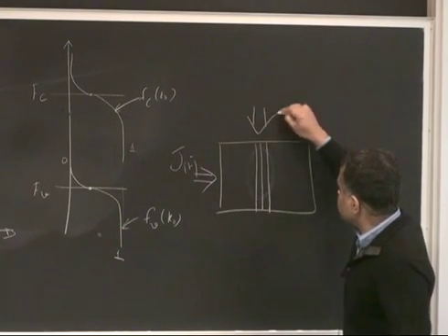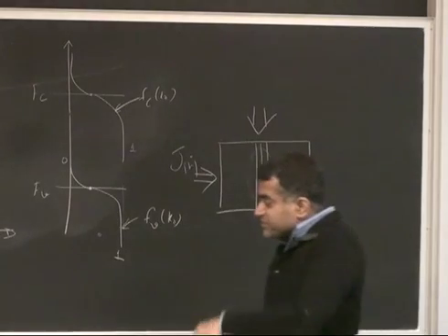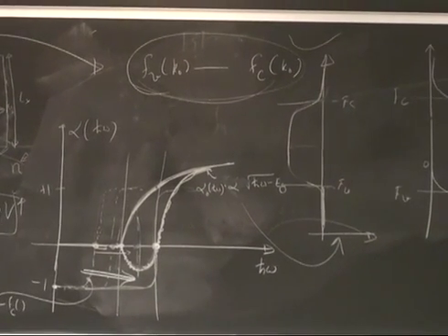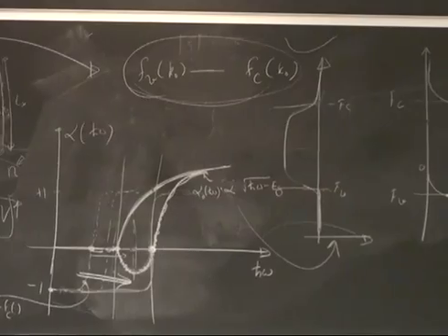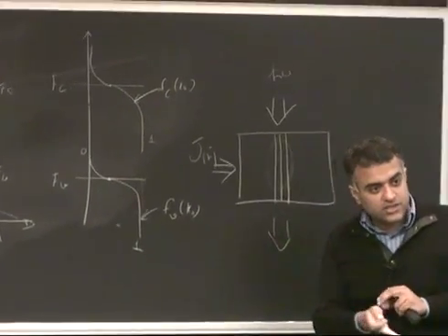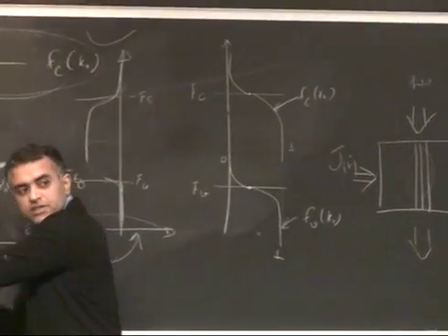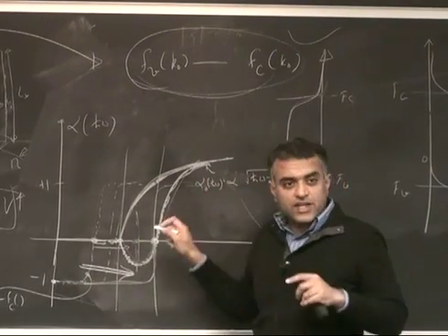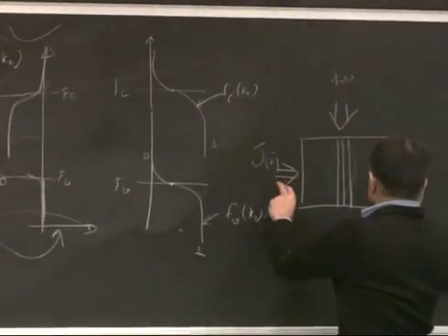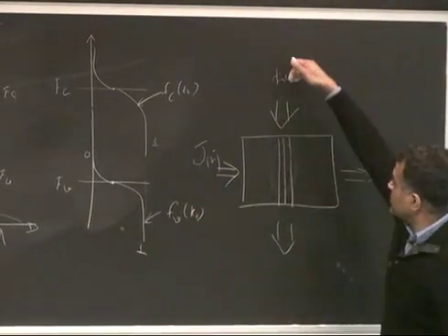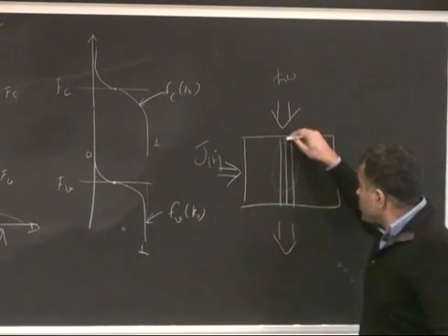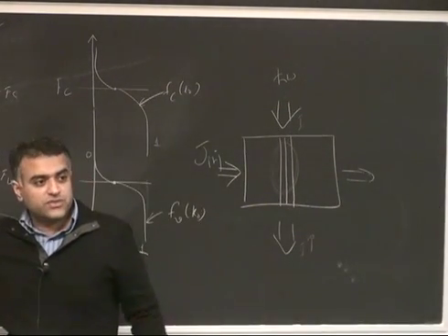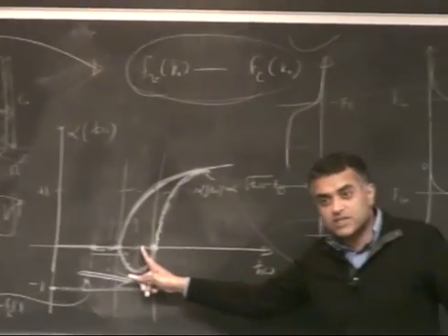What you can do is come in from the lateral edge, for example, and shine light, or you have another laser, a tunable laser, and you can see what happens as you make a pass of light of different frequencies through the region where stuff has happened. You have changed the absorption coefficient. All this has happened because of electrical injection. That's clear, right? You went from this absorption coefficient to this because of electrical injection. And now you are still electrically injecting, you keep injecting DC, and then you come in with another light source. So the amount of light that goes in here will come out amplified here, right? Because this region has a negative absorption coefficient, if the energy is matched inside this window.